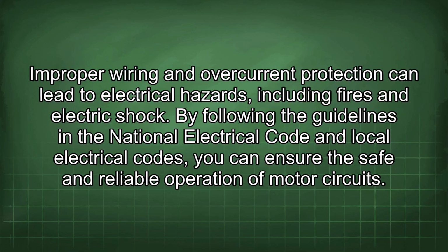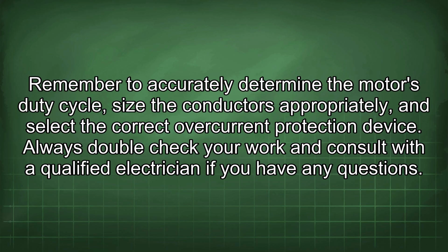By following the guidelines in the National Electrical Code and local electrical codes, you can ensure the safe and reliable operation of motor circuits. Remember to accurately determine the motor's duty cycle, size the conductors appropriately, and select the correct overcurrent protection device. Always double-check your work and consult with a qualified electrician if you have any questions.